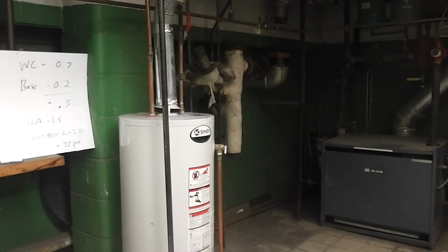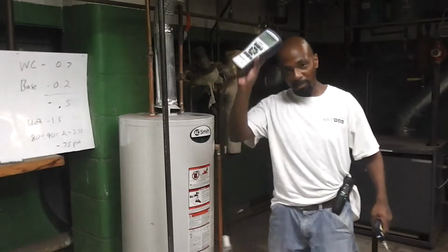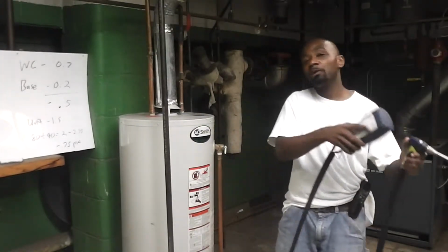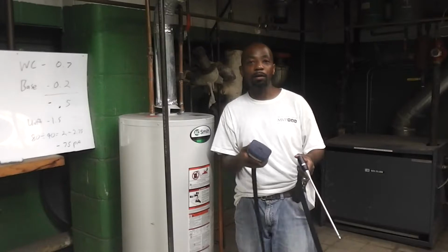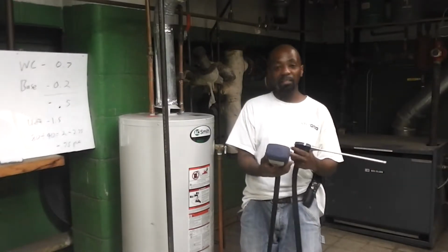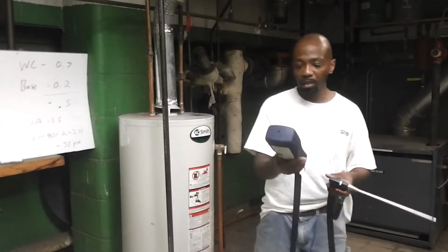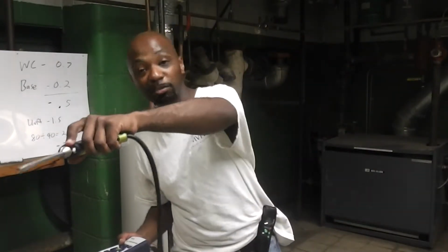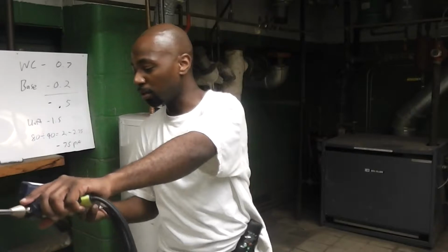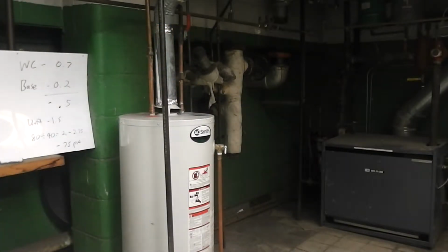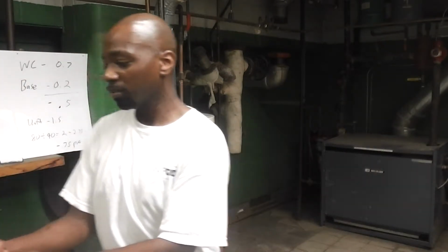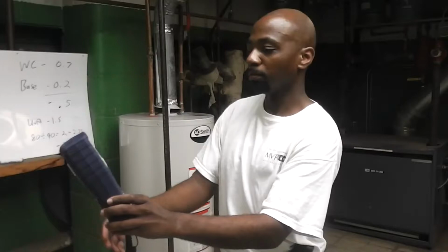The next step is the combustion analyzer. Now keep in mind, when you turn this thing on, you should turn this thing on outside, so it has a chance to actually zero out. Once it zeroes out, you can actually start selecting what needs to be done. So give me one moment, and I'll actually turn this thing on. I'm going to step outside and stick this thing outside to make sure I get a good clean reading. Alright. You give this thing about 60 seconds, and we shall begin.